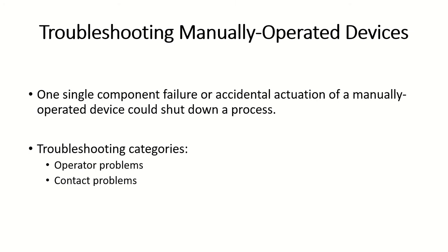And then I would also like for you guys to create a ladder diagram. I know this is really basic, and we're going to build it when you get back to class. I would like you to have a ladder diagram ready to go that shows when a green push button is pressed, a green pilot light turns on, and when a red push button is pressed, a red light will turn off. So it goes back to having a good understanding of normally closed versus normally open, and which contact position I need to use to turn the lights on or off.